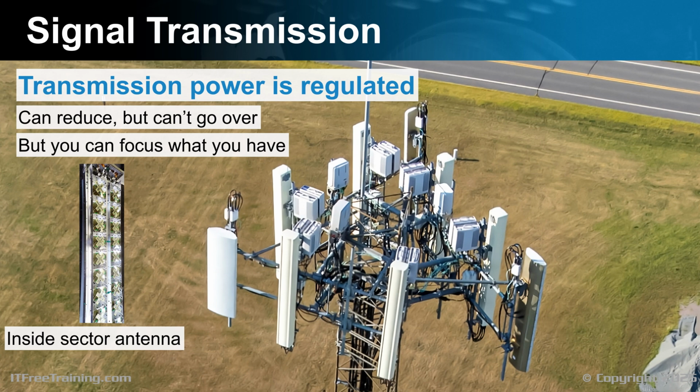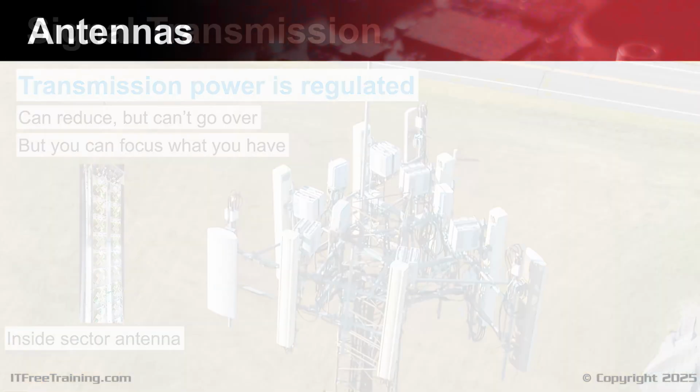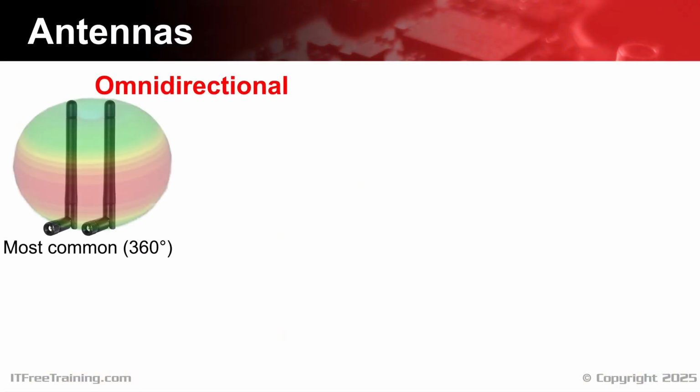The main takeaway from this is, when optimizing Wi-Fi performance, direct your signal where it is needed and reduce interfering signals. Doing this can significantly enhance the quality of your Wi-Fi connection. Improving the signal quality makes the Wi-Fi more reliable and increases the bandwidth. The best way to direct the signal is by choosing the right antenna.